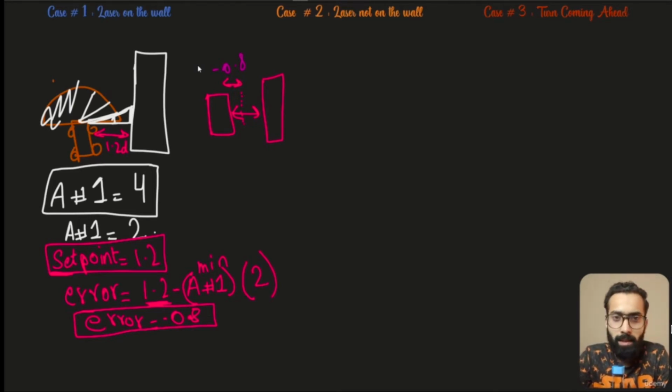We are leaving that to an open case, and we are going to say the amount of difference the robot has, meaning the error, we are going to supply it to be the angular rotation of the robot. Meaning the robot at this point is going to take a rotation towards the right of 0.8, not degrees, radians, but it is going to take a turn of 0.8. This will solve the problem of keeping a specific distance and following the wall.